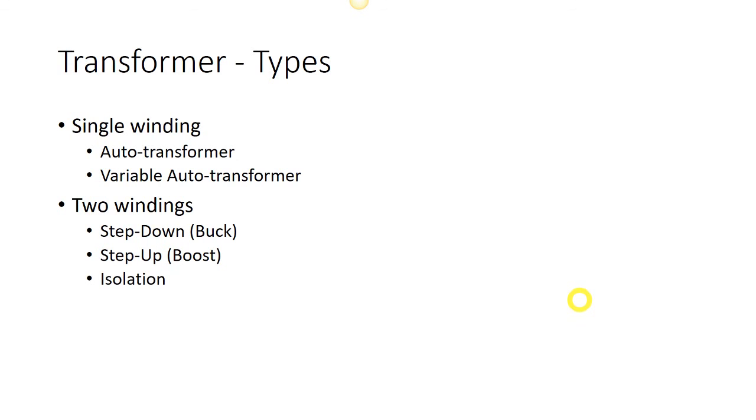And then there's an isolation transformer. That's exactly what we were looking at on the previous page. An isolation transformer has the same number of windings on the primary side as we do on the secondary side, and we use that for the express purpose of isolating, specifically grounds, and we use those a lot in control systems. When we bring power into a control system, we don't bring a lot of the noise that we can find in building steel in the plant, so we will isolate it through an isolation transformer before it actually comes into the control system.